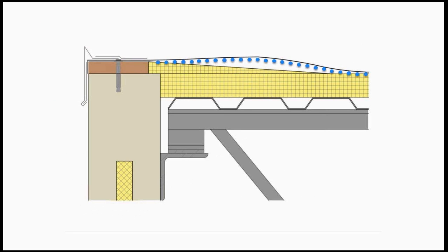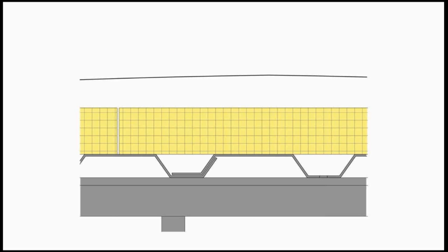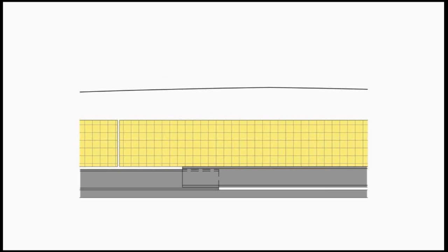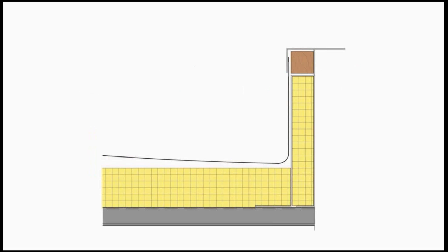So when it inflates, the moisture from the air condenses on the underside of the membrane, like we show here. It can pull in around the edge of the joist through the deck. Again, at the perimeter, there is some air that leaves to the outside. In the field of the wall, all the splices and burn holes, and then it goes to the joint in the insulation. Again, it's only one layer, not two layers of staggered joints. And if we look at those splices, the seams in the other direction of the metal deck, it goes through those as well.